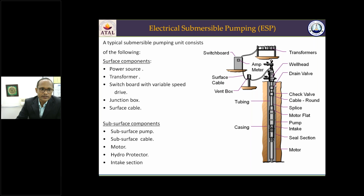Above the check valve, there is a drain valve. This drain valve is used to drain the liquid. Suppose we want to take out the tubing. Taking out the tubing as well as the fluid inside will be very heavy, thousands of feet of fluid. So the fluid is drained from here so that we can lift the empty tubing, and the weight to be lifted decreases. There are other components also, like the centralizers. Centralizers are used so that the pump is centralized inside the tubing.